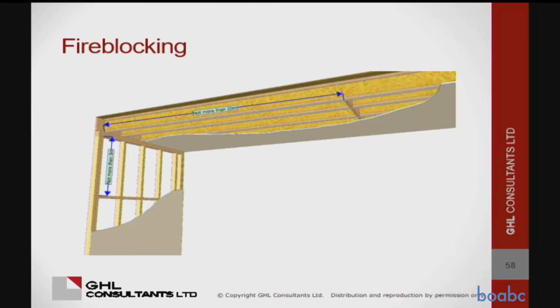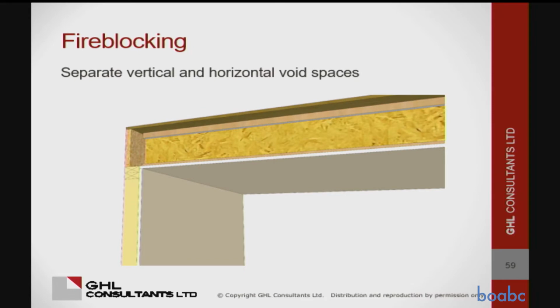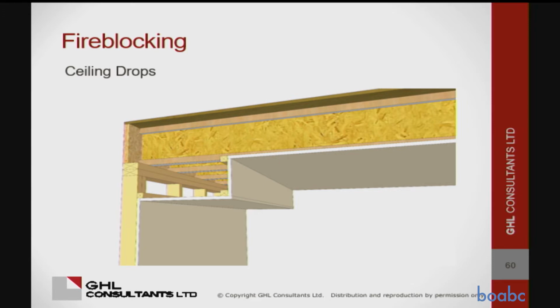Oh yeah, so obviously the issue here is the top plate on the wall is, once everything's clad with gypsum board, the top plate's going to separate the vertical from the horizontal. Like that. But then when you do this, now the wall cavity is open to the ceiling cavity. And this is what the code's trying to prevent.